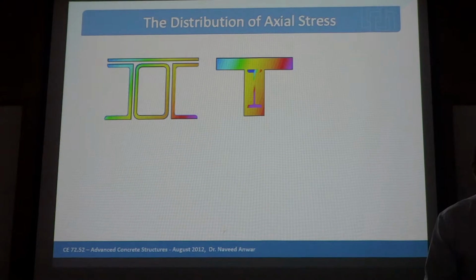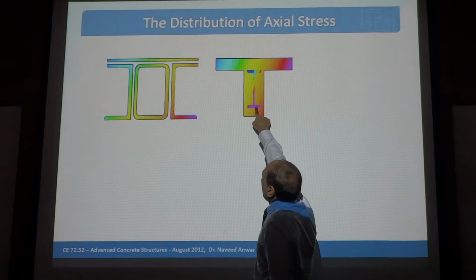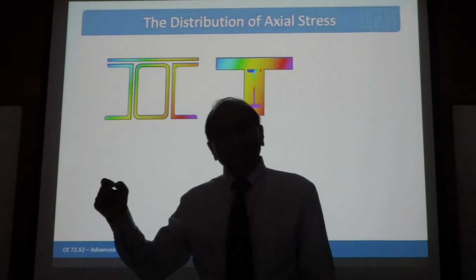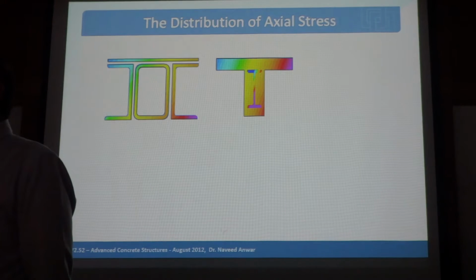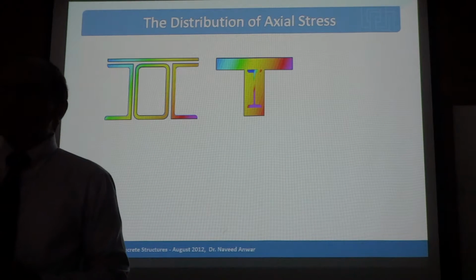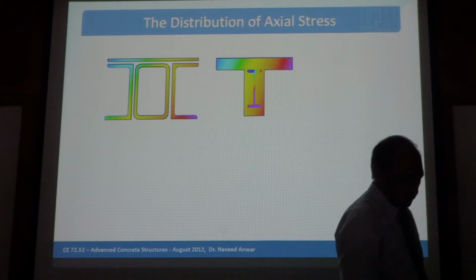And now you can get the stresses in composite sections. So you can see from here, stress jumped in the steel section inside concrete because you multiplied the stress at that location by n. So 10 times more stress at the same location as concrete next door, right? But you can still determine this and you can calculate all the stresses everywhere.